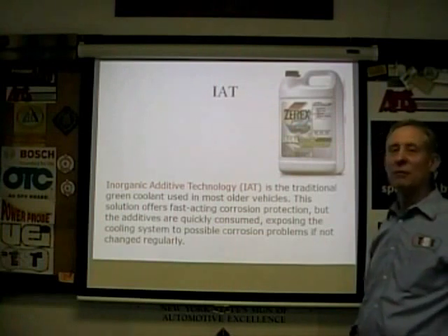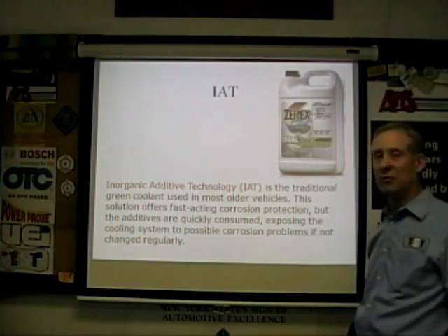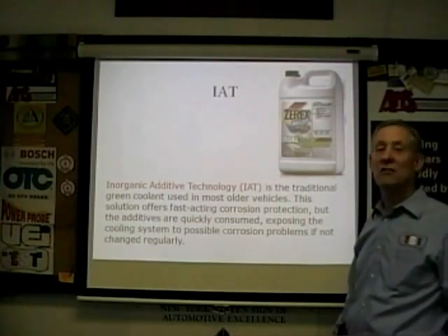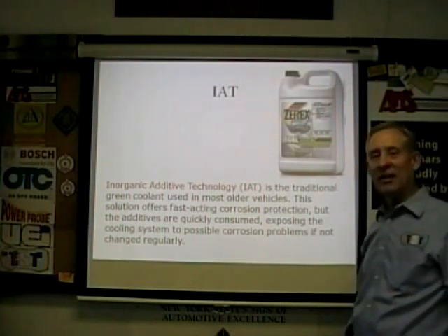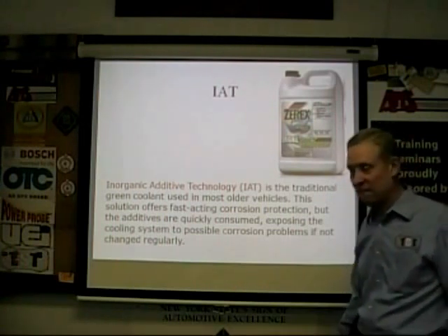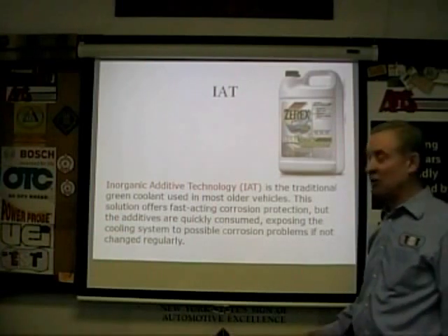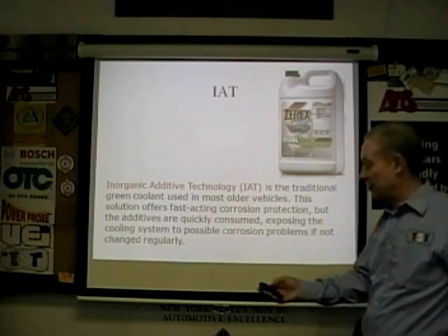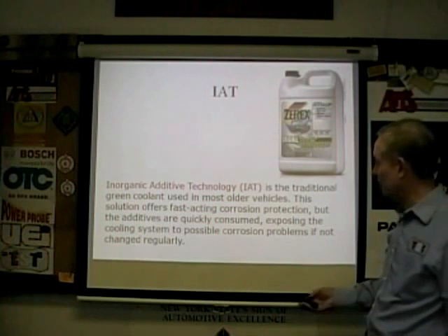And I was doing BMW exclusively at that point. We had unusual failures in BMW. After a few years of those, where we had radiators that looked flawless, no broken fins, no plugged anything, and yet the coolant leaving the radiator was virtually the same temperature as the coolant getting into the radiator. There was no heat exchange going on. They came up with their own coolant. I started using their coolant with distilled water, and the radiators lasted virtually forever until they started raising pressures and temperatures and the plastic housings blew apart.